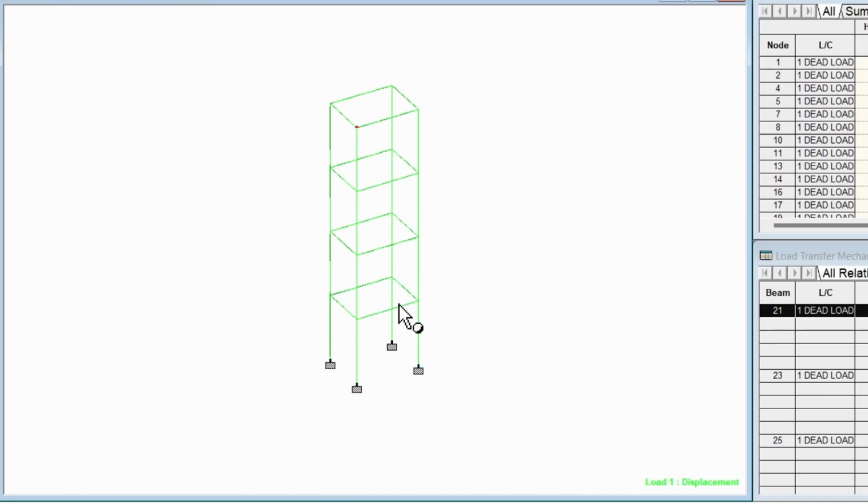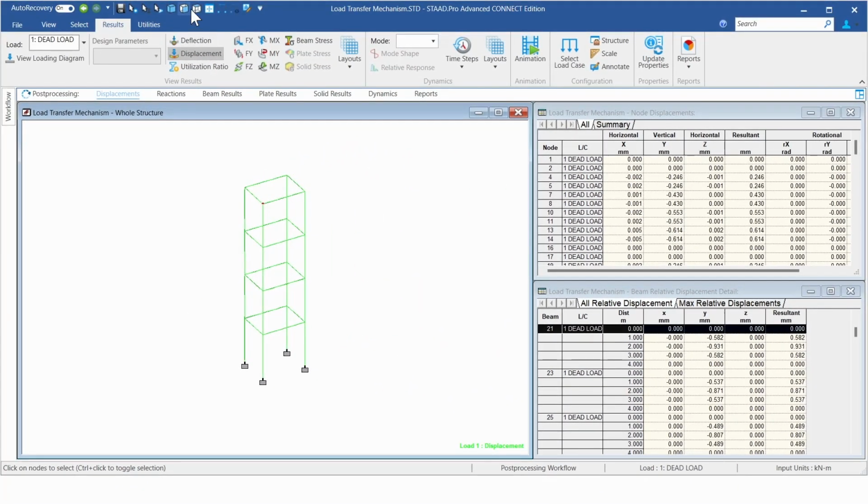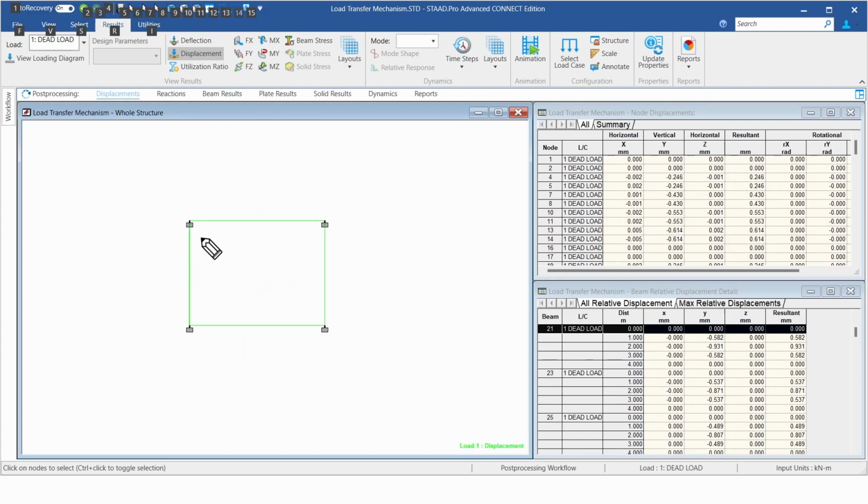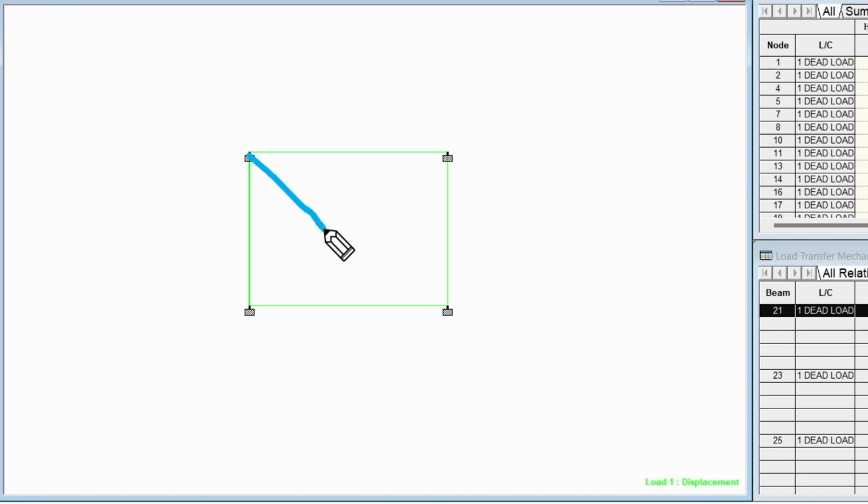And if you don't understand that, I'll quickly take you to the top view again. What is happening for each of these members, or rather beams, is that this beam was taking just this load, this was taking this load, and each of these was taking the trapezoidal load. So if I were to just look at this node, or rather this column, the load transfer was going to be half of this entire triangle, because this beam was going to be taking the full triangle. So this part is going to be taking only this half triangle.